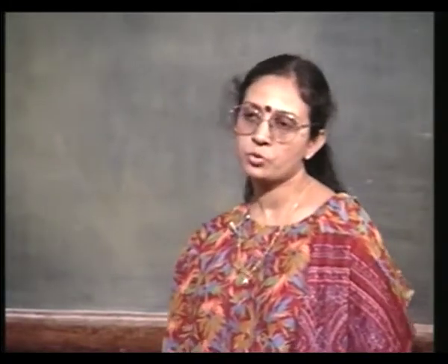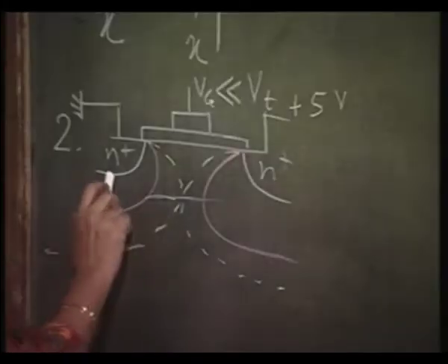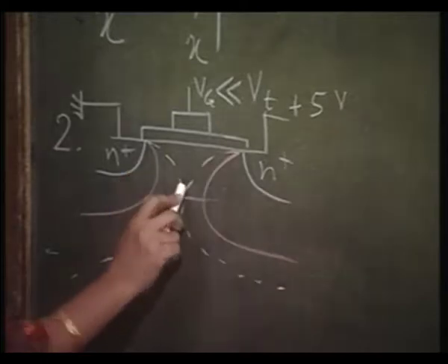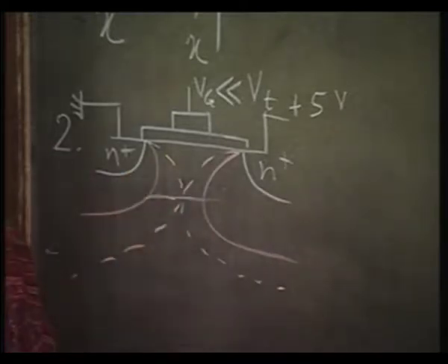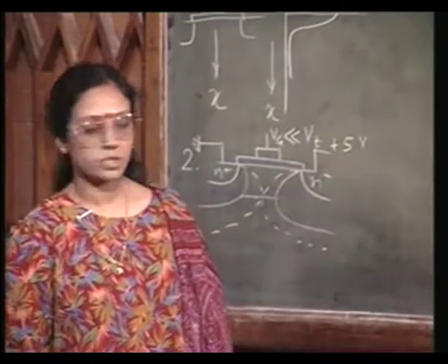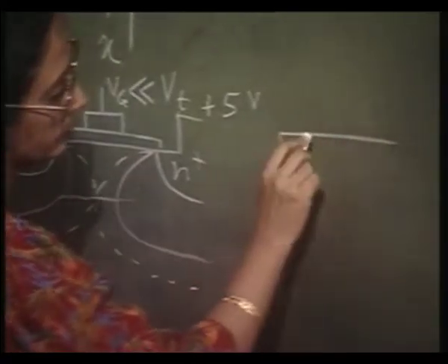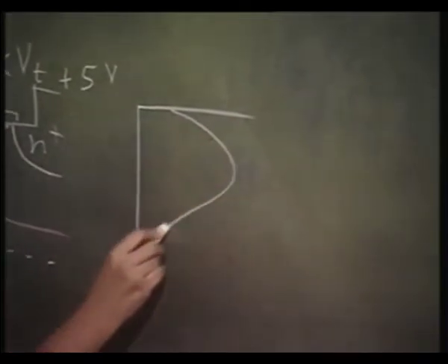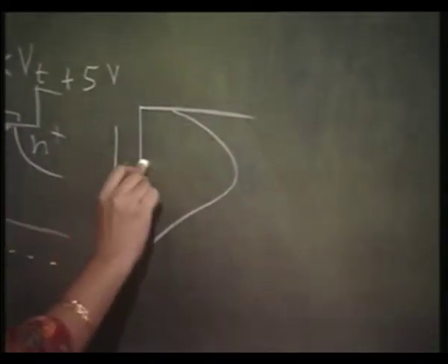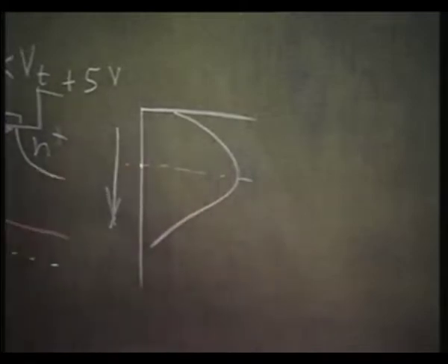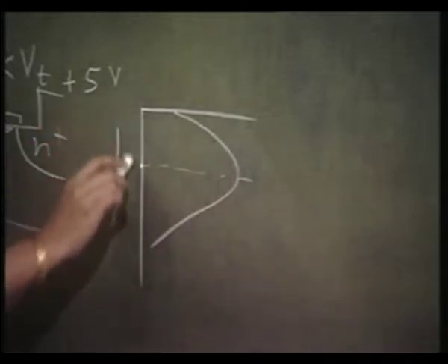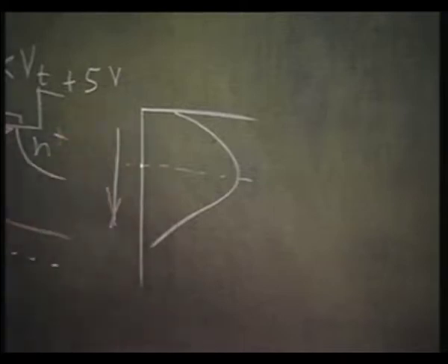Okay? And this boron implantation peak should be approximately at the source and drain junctions, approximately here. This is the point where it is most likely to merge. So, the deeper boron implantation should have a nature like this. This is approximately at the source and drain junction depth, right.